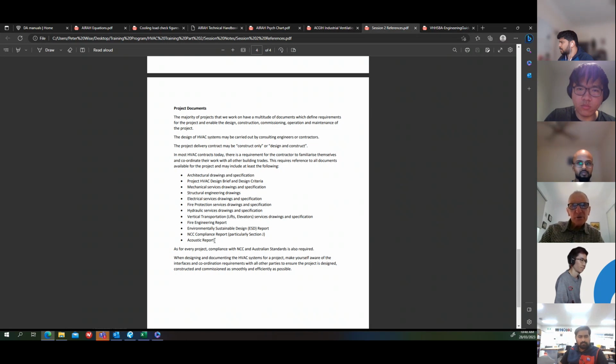Let's say you're doing something that's noise sensitive, like a sound studio or something like that. They might say that they want a noise level of, let's say, NR25, which is very low. And they'll say in order to achieve that, your supply air duct velocities need to be 4 meters a second or something like that. And they vary in the content that they give you. They might just say, we want NR25, and it's your responsibility to design the system to achieve that. So then you've got to do the acoustic analysis.